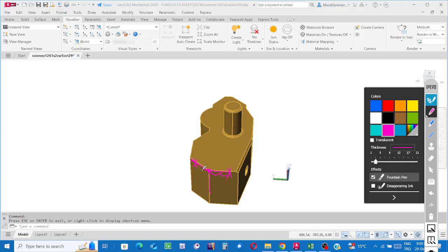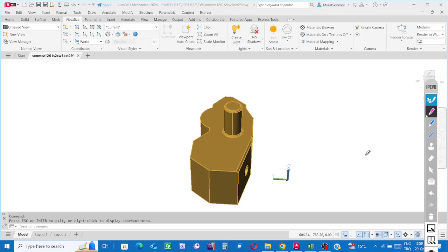How is it done? In sequence, first coincide the x-axis with this edge and mark the first point using this distance. And then coincide the x-axis along this edge, and then mark the second point; coincide the x-axis along this edge, mark the third point. After marking the points, we can start the polyline process and join the points in sequence. Okay, then let's practice on such an example. Move the